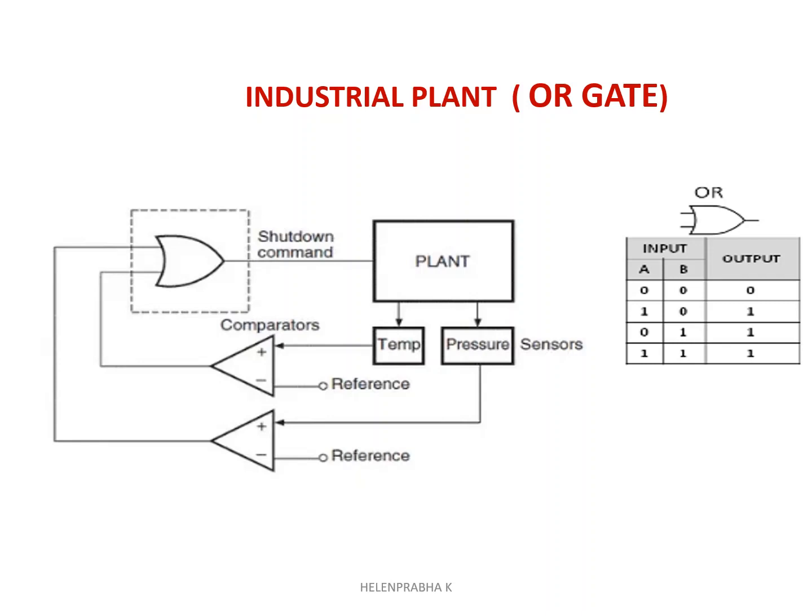Or if any one of the sensors is more than the reference value, the comparator will give output as 1. Then any one of the inputs of this OR gate is 1, then the output is 1, and automatically the plant will shut down. So the simple OR gate will help more, right?